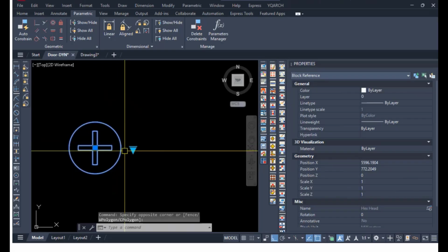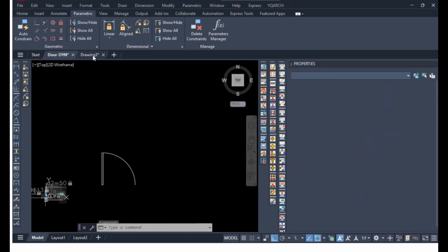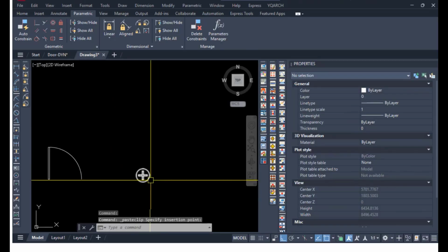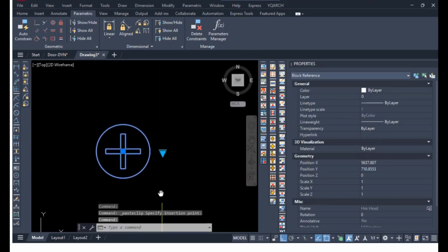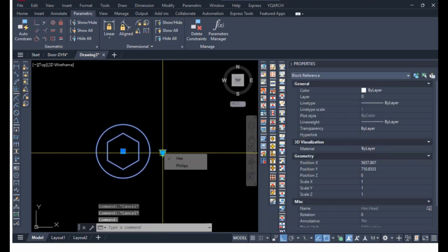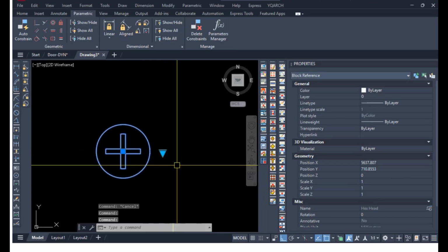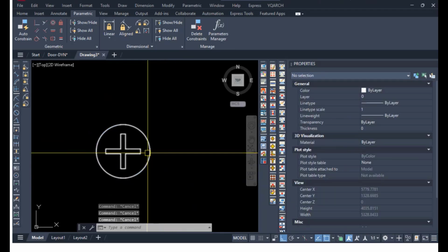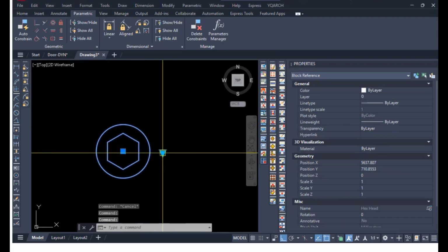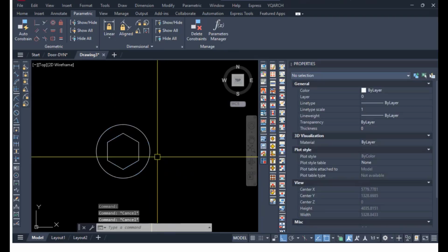okay, I will copy this one because I don't want to create from scratch anymore. This one, because this is the visibility hex. You see, we can change the head of the screw from hex head nut to flat head. Okay, flathead screw. Easy like this. We call this kind of dynamic block the visibility. How can we do this?